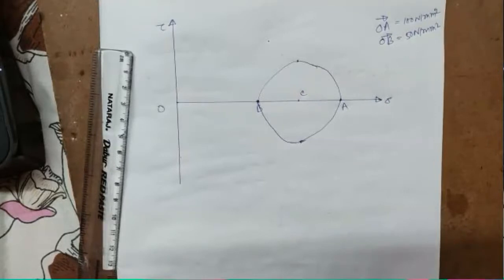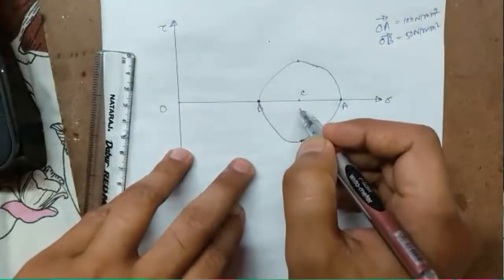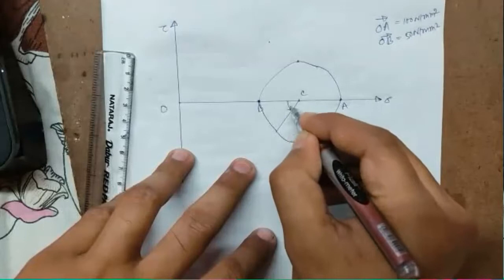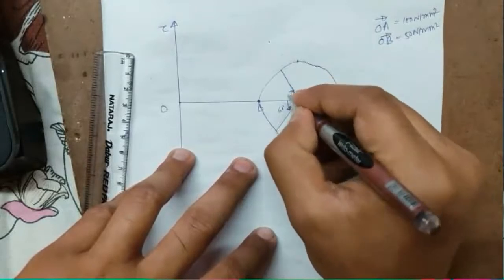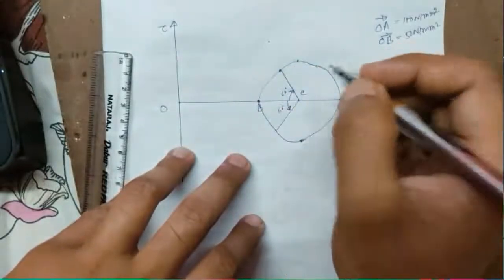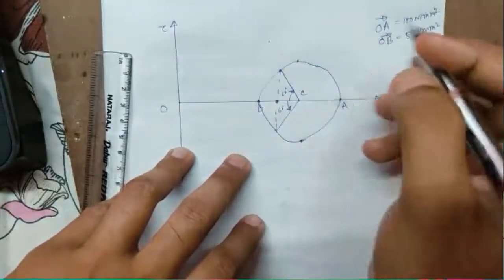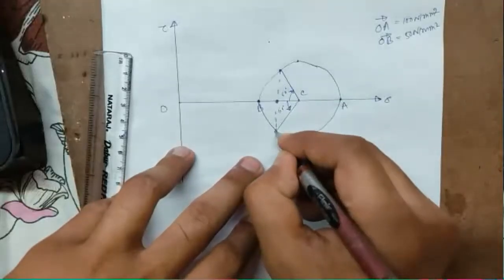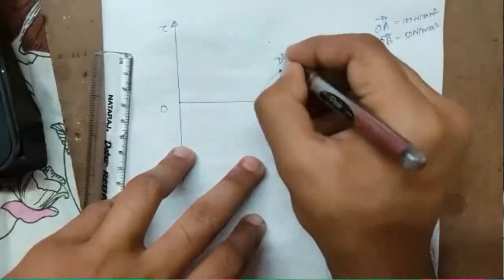So the angle is at 30 degree. Here on the Mohr circle of stress, it will be at 60 degree. So either you go counterclockwise 60 degree, or you go clockwise 60 degree. Now this point, when you get, you just draw perpendicular. So when you are going counterclockwise, you get this point, say this is D. When you get clockwise, you get D dash.